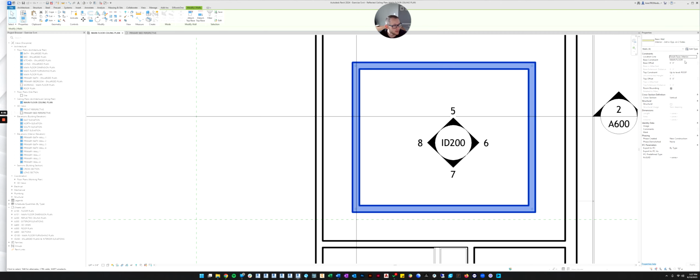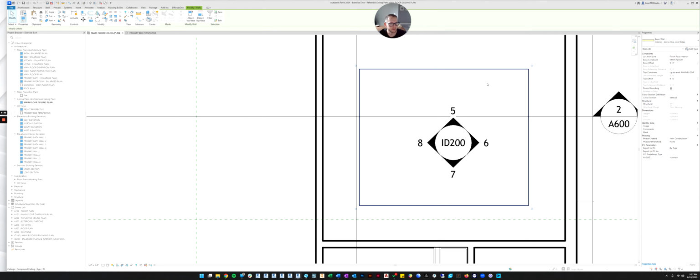And now let's have those start 9 feet off of the main floor, and they will go also from the main floor. So the top constraint will also be main floor. Sorry, main floor, and it'll go 9.5. So 9.5 feet from the main floor is where the top constraint is, and the bottom constraint is 9 feet off of the main floor.